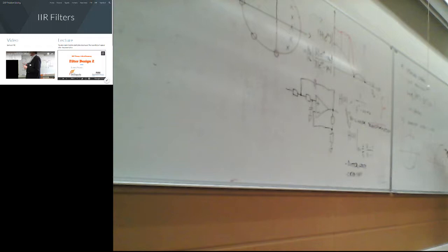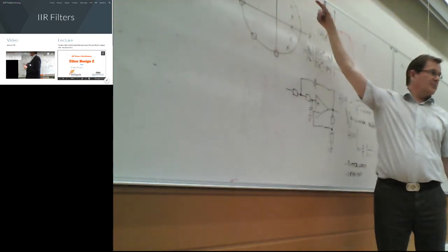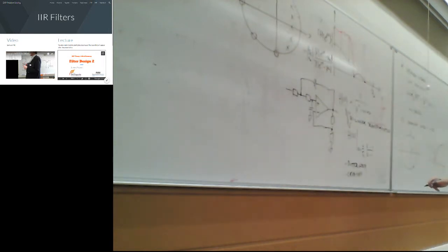It's not symmetric, and it's quite wide band. However, you can improve this one by adding, well, just like here. You actually add some gain by putting a pole close to the unit circle on the same angle and the complex conjugate pair.